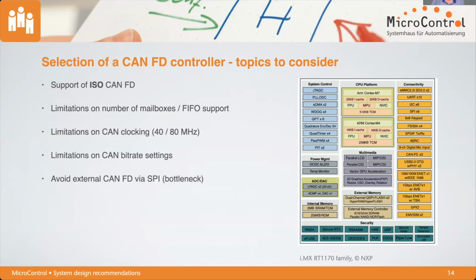These are the old-fashioned non-ISO CAN-FD controllers. So don't be surprised if a non-ISO CAN-FD controller doesn't work in your systems. They are still sold, but don't select them.